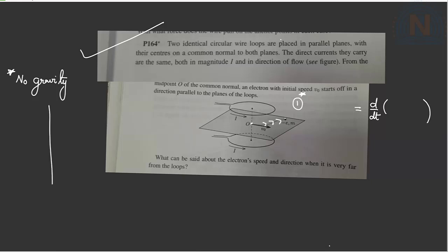Now, anybody under any confusion can always look into the top view. So if you observe the top view, you will see this point O, and some general curve. Obviously when the particle will be at general R and theta, it will have a VR velocity, it will have a V theta velocity. Whatever curve it is following, don't worry. But general velocity will have two components, dr by dt and r d theta by dt. VR and V theta. Now my point is, the angular momentum of this particle is provided by V theta, V tangential, right? So you should say this is m V theta into r. Remember, this is general R, general V theta. Because your radial component of velocity, that cannot provide any angular momentum.